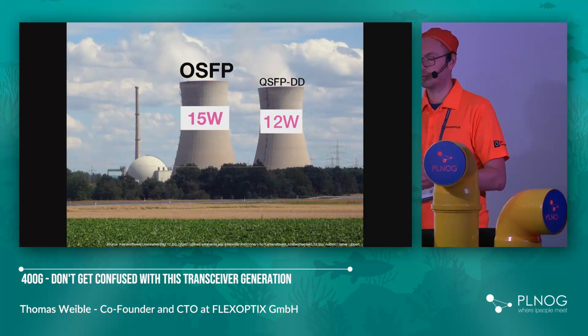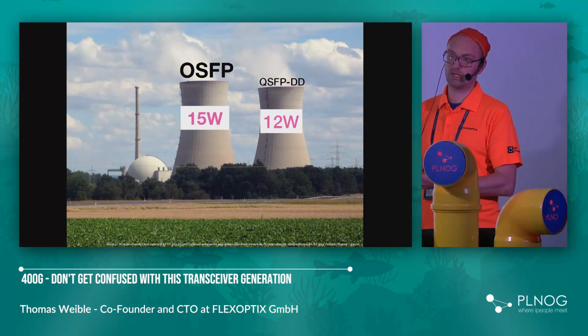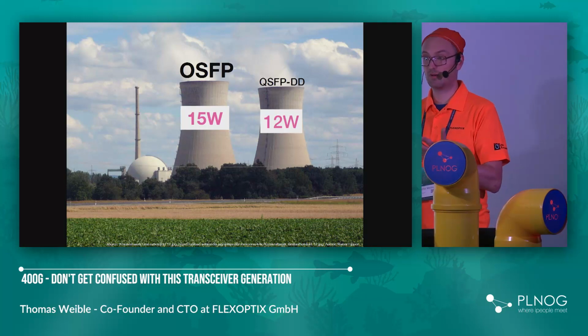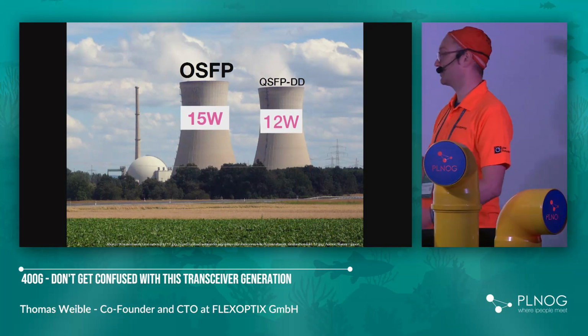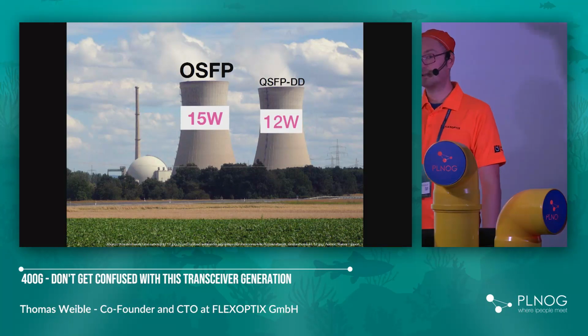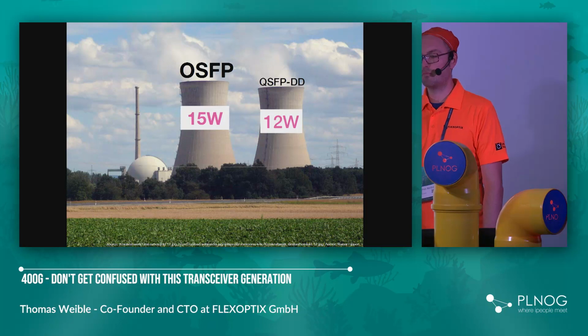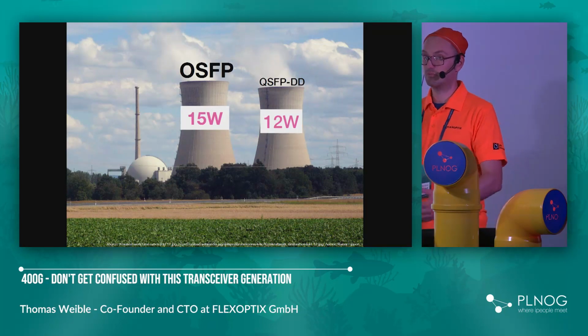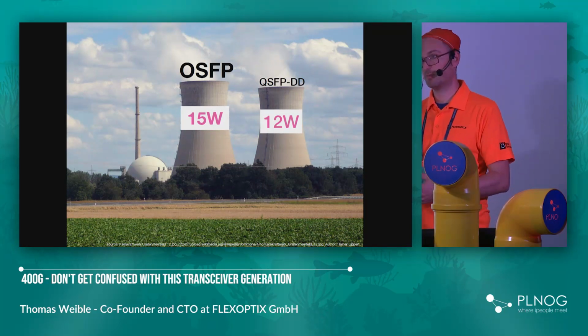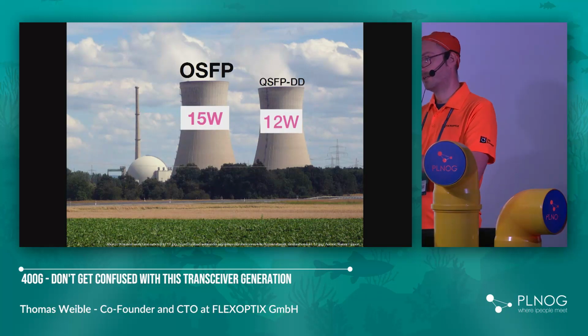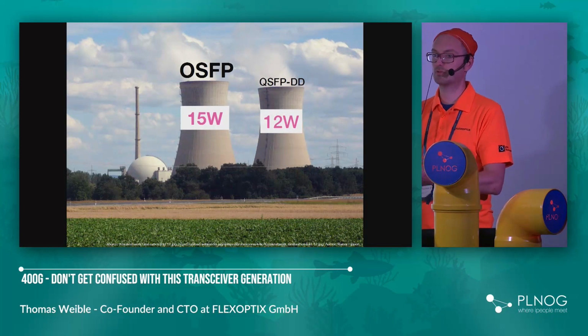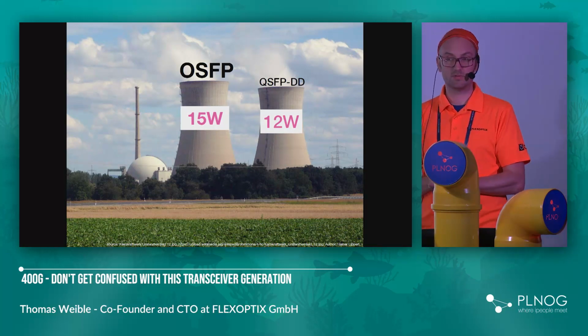It's really a tough job to get that into a QSFP-28 form factor, which is only allowed to have up to 6 or 7 watts. So these lessons were learned for OSFP and QSFP-DD, to increase the amount of power you can feed into that transceiver. Currently they are not available, but looking down that glass bowl down the road for the next 2 or 3 years, we might see coherent DWDM solutions for OSFP and QSFP-DD.